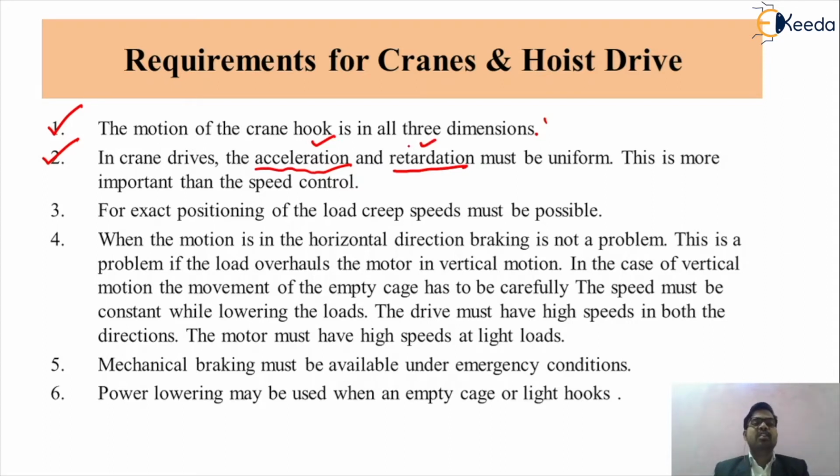So this is a very important requirement while we are designing or selecting a drive for a crane and hoist drive. Then the third requirement will be for the exact positioning of the load; creep speeds must be possible, because as we have seen in various applications like different manufacturing processes, we have to put some object at the appropriate place. So positioning control is very important while we are selecting the crane and hoist drive for a particular application.